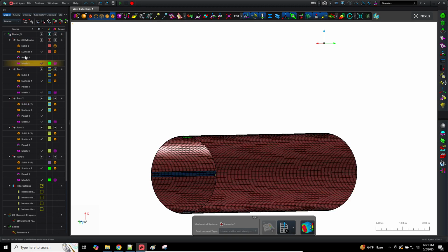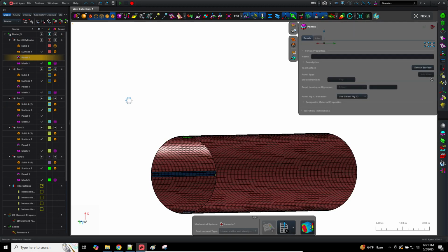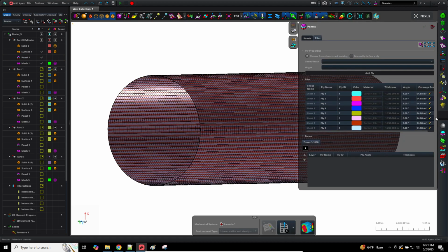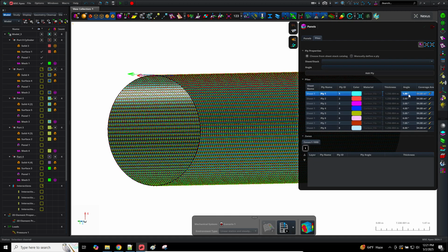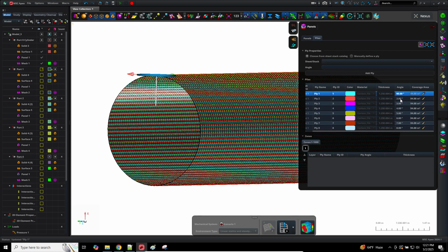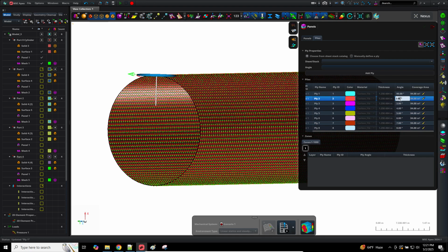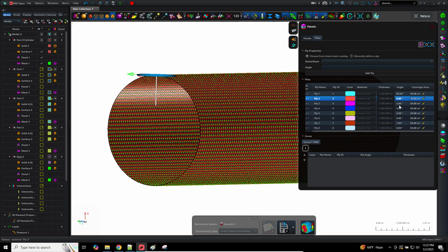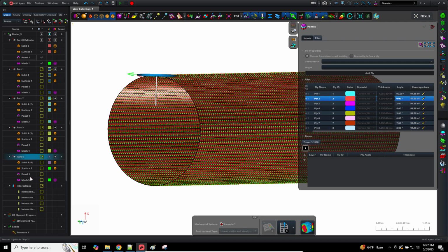Alternatively, you can come here in Apex and you can do the edit manually here. So here, double click on panel 1, go to applies, and you can do that here. So you would double click here, you would say, okay, this is 90 degrees, and then there's a delay period here. So here 0, and so you can see the process is a little time consuming here. I think this is what I'll do.